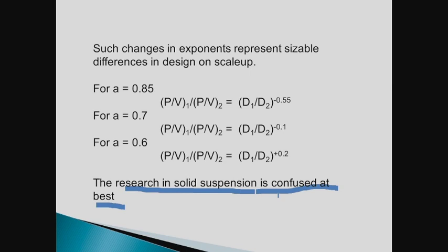And their surface behavior is variable. There are sort of like 7 different surface chemistries, and then you have agglomeration that can happen, and then the fact that the surfaces aren't pure gives rise to problems with suspension of solids, or I should say it this way, you may have unforeseen problems on scale up of solids.